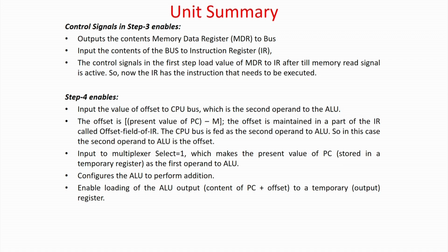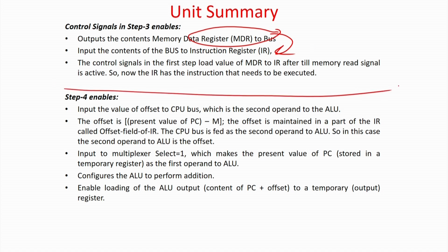The 3rd stage is also very similar. The 3rd stage basically says that the memory read is okay. So, basically the output of the memory data register is going to the instruction register, as simple as the fetch. So, up to this is more or less similar, that is you fetch the instruction and put it in the instruction register. Only one extra thing we do here, you just keep it in mind, that we will store the value of program counter in a temporary register Y.